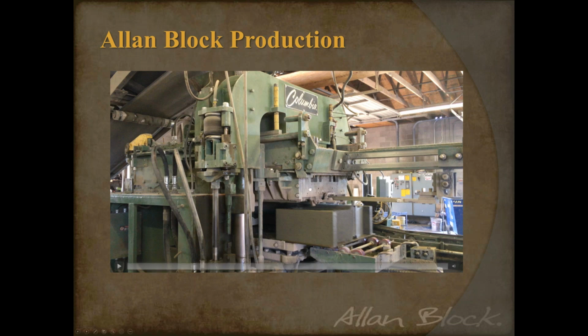The liners bolt to the side of the box, and the liners are there to make the shape of the Allen block or whatever block they're making. This is a core bar. You're going to see in the video, it'll slide in and it will be left in place as the material is brought over and dropped in, and then the head assembly will come down and vibrate and compact the material into the shape you're seeing. And then the core bar will be pulled out. What will be left is a void down the bottom that we call the notch at the bottom of the block, and that's how that's formed.